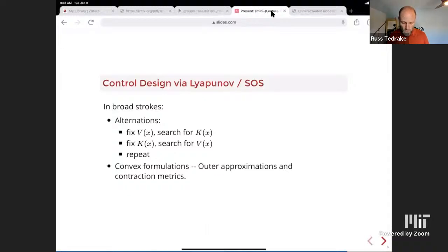Let's decide if we want to go into it or not. But let me just roughly say, one of the reasons is that what you'd like to say is, for all admissible U, something happens, okay? The control Lyapunov function statement is actually very hard because it says there exists a U for which my V dot will go downhill inside the set. That turns out to be very hard. There exists is a hard thing to write with these sums of squares, okay?